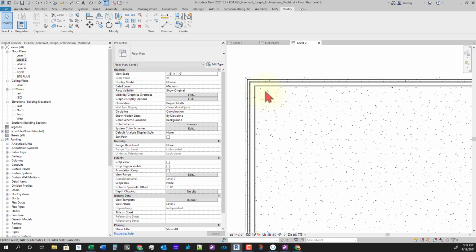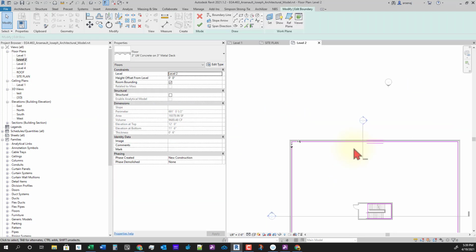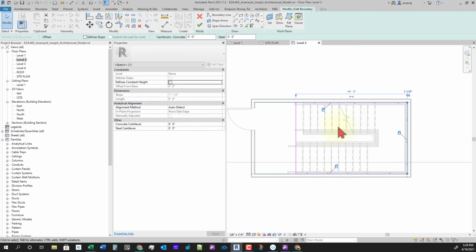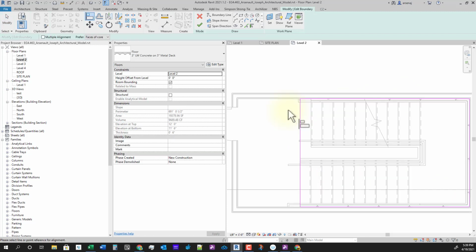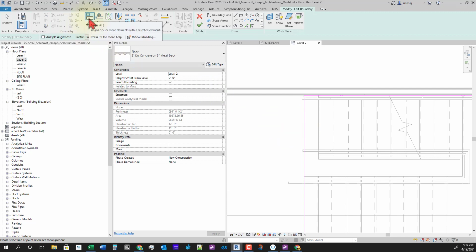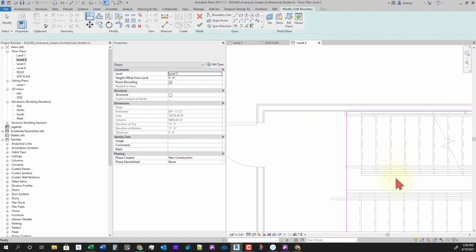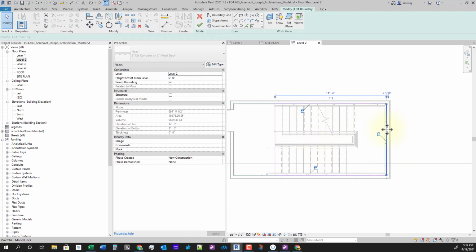The other thing we'll do in here, and let's see if I did it already, is the same thing for the stair opening. It looks like I did. So I did the same thing where I hit Align, AL, or up in the Modify tab, you can hit Align. Select the face of the chipboard on this instance, and then hit that. And then make sure they're all locked.